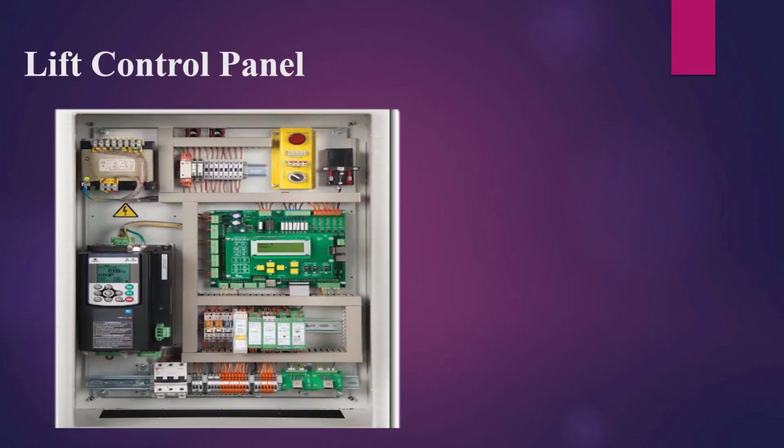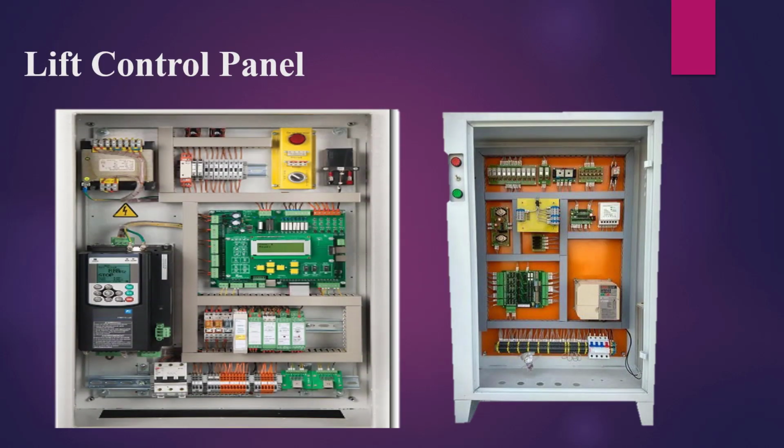Lift control panel. For passenger lifts, movements must not be abrupt and perfect positioning is required independent of load. A variable speed drive is the most suitable solution to control speed and positioning. The variable speed drive also ensures braking control, which is synchronized to the movement. An escalator, with frequent starts and stops, tends to stress mechanics. An electronic speed drive ensures acceleration and deceleration while limiting jerks that can accompany high torque applications.